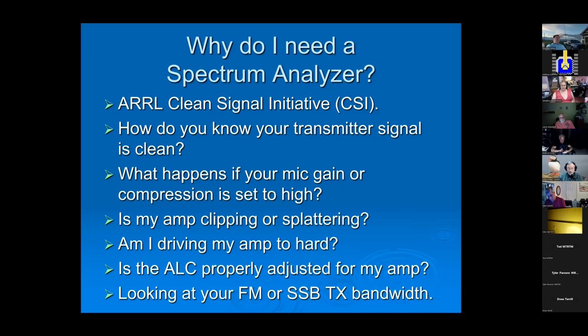ALC. If it's properly implemented, all it should do is drop your output. But I keep hearing guys talk about how sometimes when ALC kicks in, it can also cause distortion. I haven't seen it, I haven't experienced it, but this also gives you the ability to connect everything up, and while running ALC, you can adjust that knob and determine when you're driving that thing too hard.